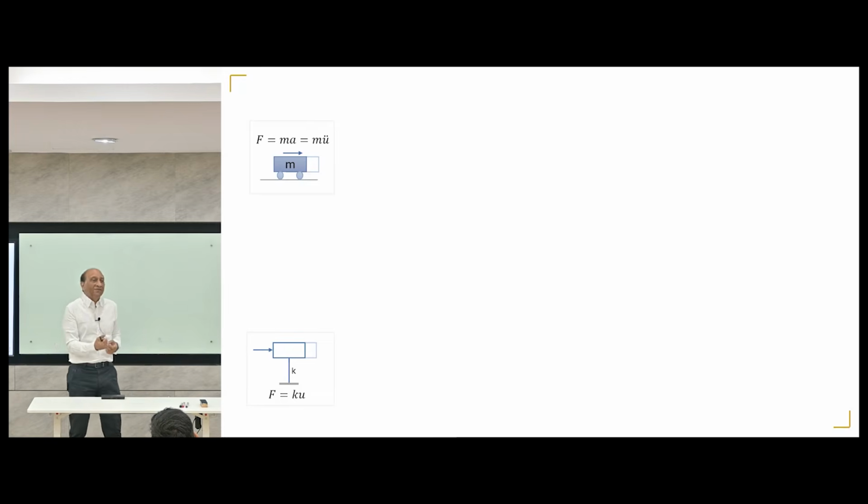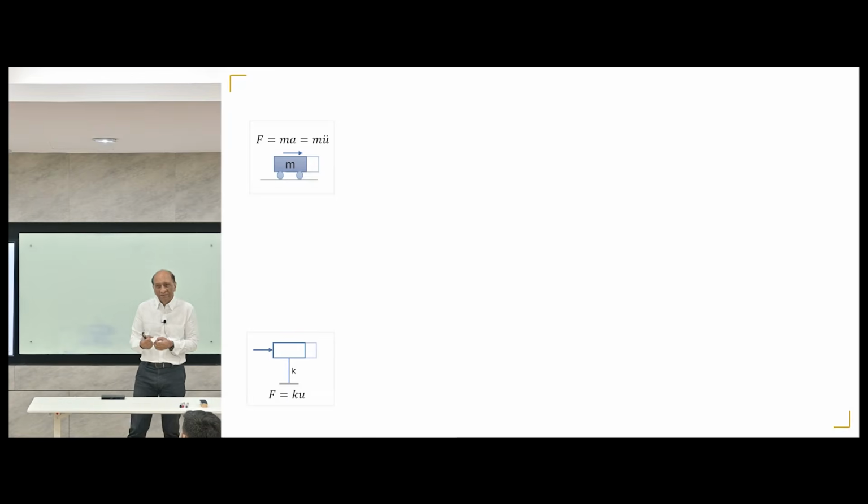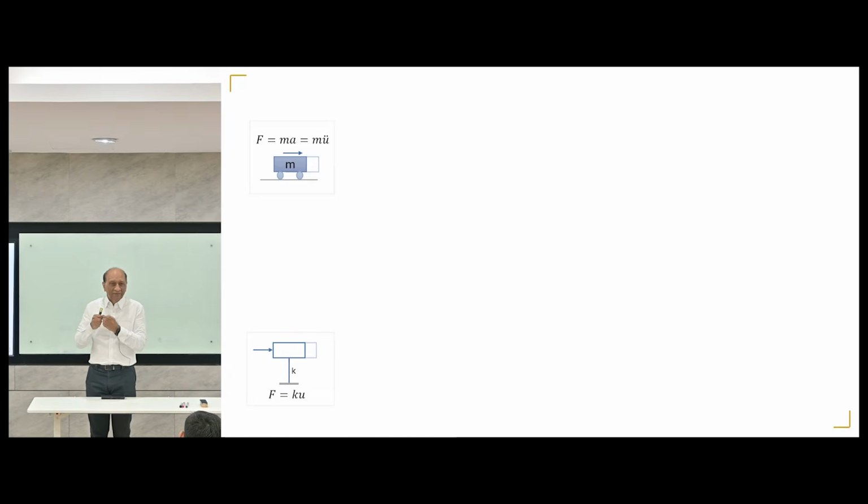This one is saying, no, the body is actually fixed, but I want to move it. So if I move it, it will deform. The body will now have deformation, and that deformation is proportional to the force, and the stiffness is the proportionality. So now we have a different look at the same thing. Mass is ignored, body is back, and now the force is proportional to stiffness. In one, the force is proportional to acceleration, with mass kind of constant. In this one, the stiffness is kind of constant, and displacement or deformation is proportional to force. So two very different views of the thing, right?